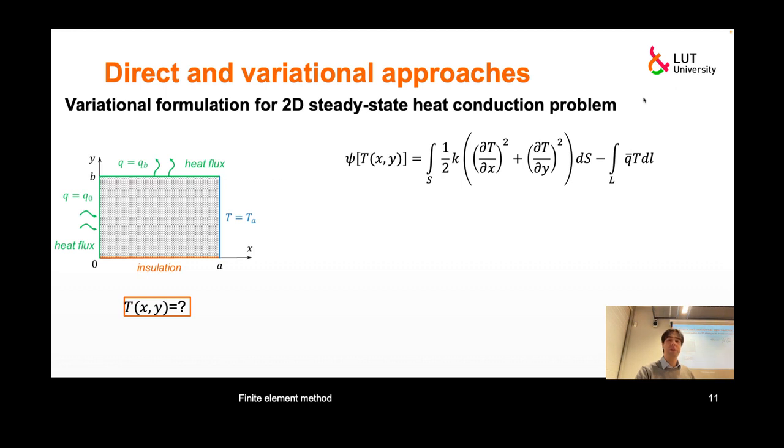So I formulated it in a general way here, like integral over entire boundary, and there is some specified value of heat flux. Okay, I will be using two particular values, Q sub 0 and Q sub B, for my two boundaries with non-homogeneous boundary conditions of this type, but this is general formulation. So the boundary conditions could be different, it would still be the same.